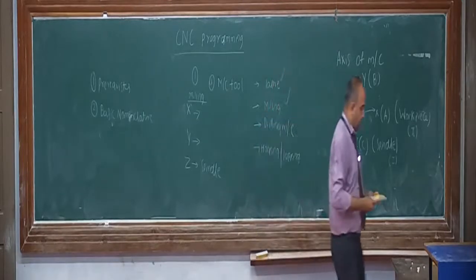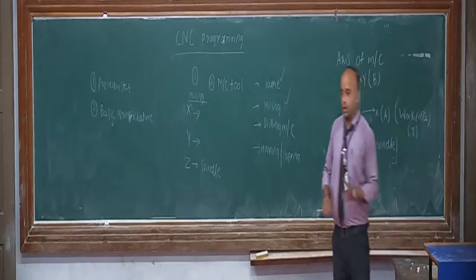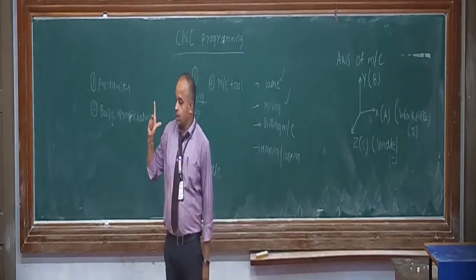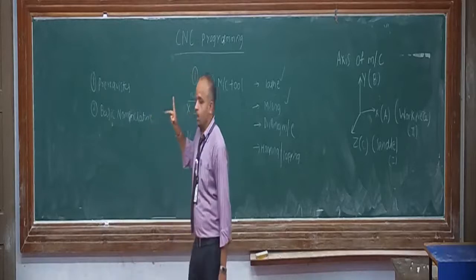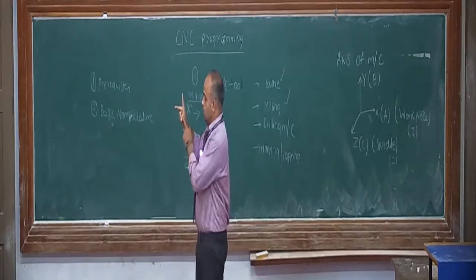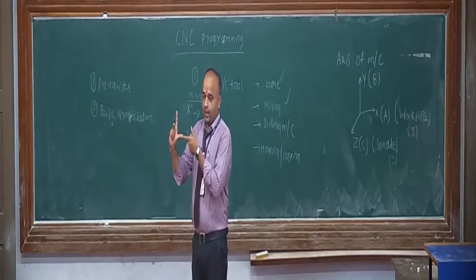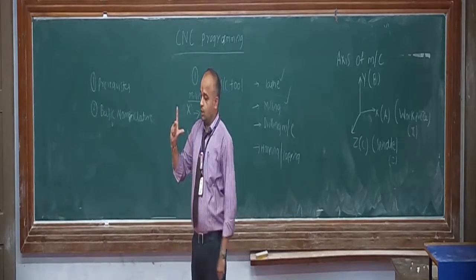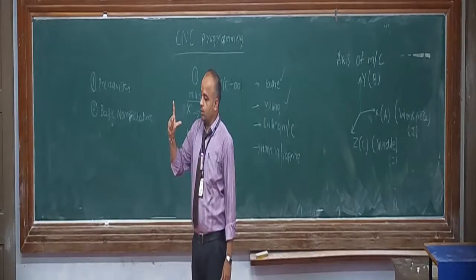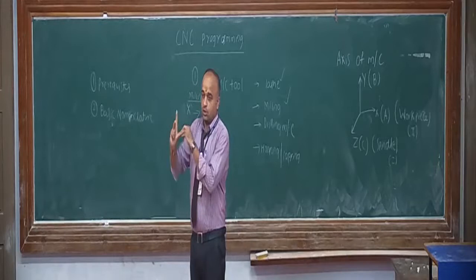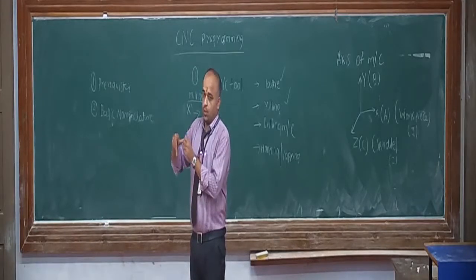Now, just observe here carefully. Whatever the condition, your x does not change. Now just understand, this is your horizontal milling machine. I'll put it sideways. See here, this is your bed. This is a horizontal milling machine. So what I'll do is convert the horizontal milling machine to vertical. Now if you just see, the x-axis position is not changing. Only what is changing? Either y or z.